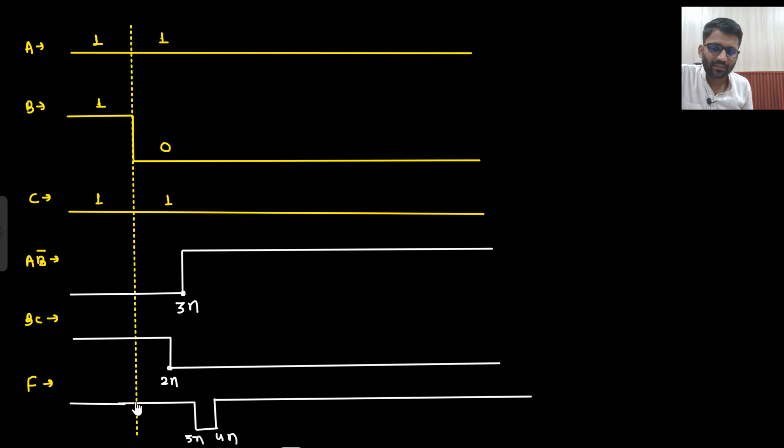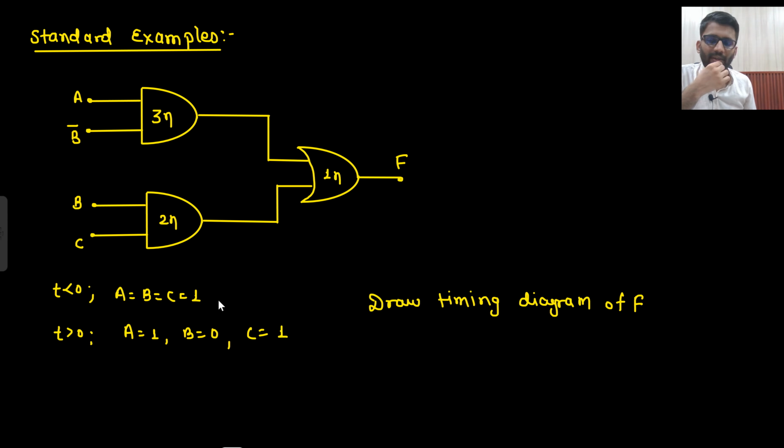These timing diagrams, that's why we solved it very quickly without thinking of much explanation, because we have already studied them. So from 1 to 0 and then 1. What do you see? Which kind of hazard is that? Always you are expecting it to be 1. Why always you are expecting it to be 1? Because in this case what will be your output? 1 into 0, here you will have 0, 1 into 1 is 1, 0 plus 1, 1.